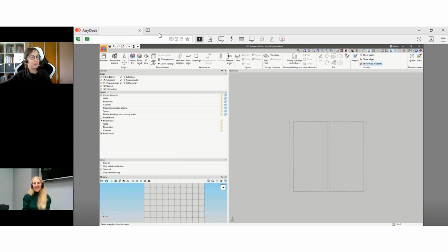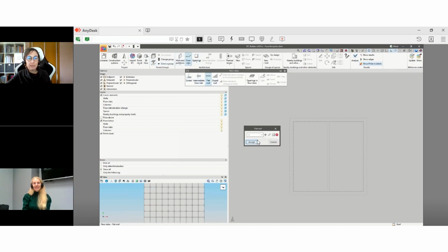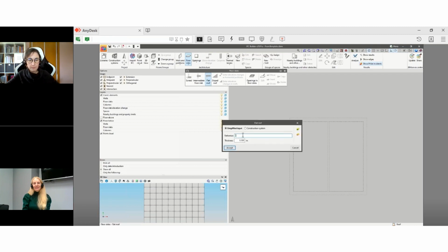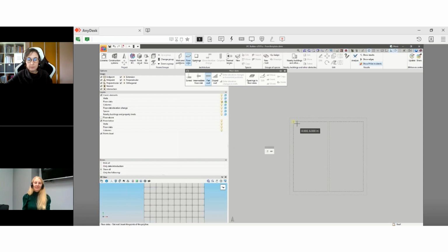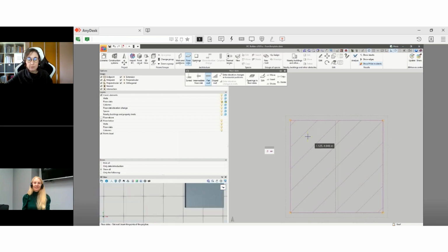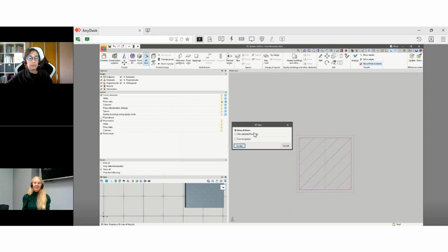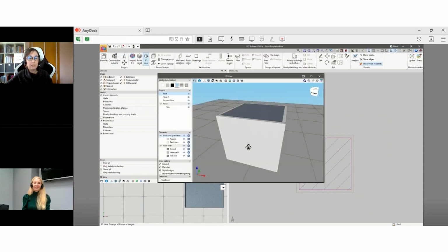And then, just because I'd like to finish the model, let's put a roof, okay? Let's put a roof on this building. There are many ways of doing this. I could copy again, use these options, but I think it will be faster to click on flat roof and create a flat roof one. If you see, I can capture what is underneath. So I'm using this reference, so now I have the complete model, okay? So here it is.